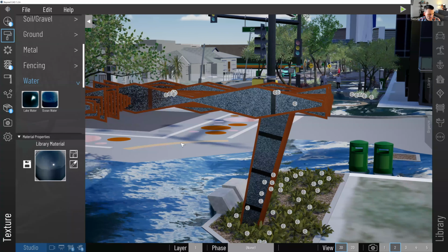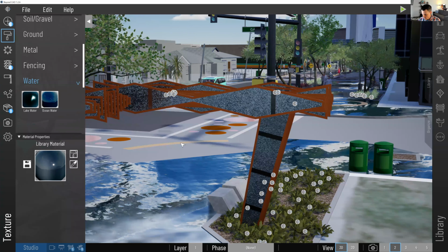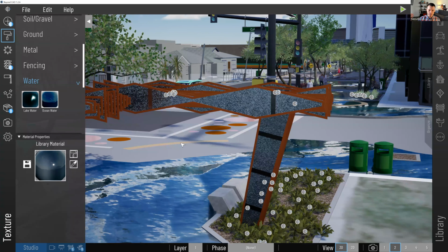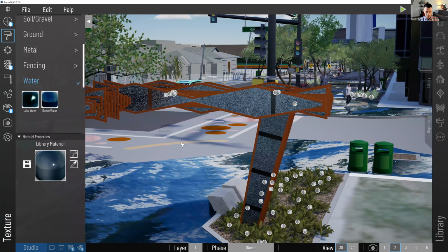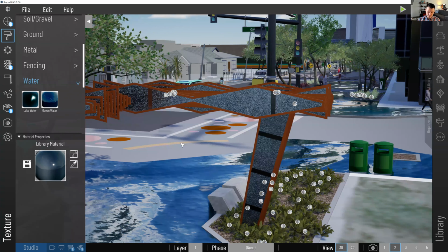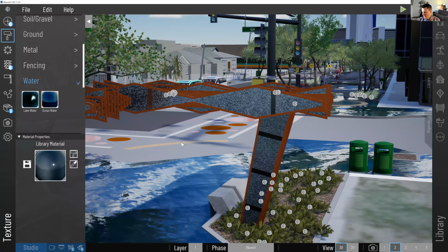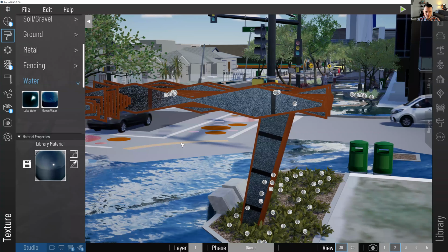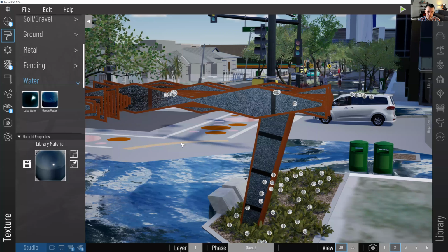Yeah, watch that video. You actually need to export an OBJ, which is just a weird quirk of it. The FBX textures don't come in correctly. The textures all come into BeyondCAD in a weird way, like they're just numbered. I don't know if Infraworks just does that in general. So it's not super clean, but you can organize it within BeyondCAD, and then you can just apply the textures on top of it. So that video shows step-by-step how to do it. And that's probably the workflow that we've seen the most users excited about, as far as it consistently works.